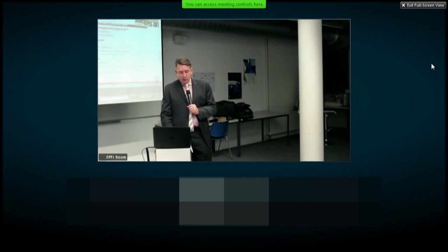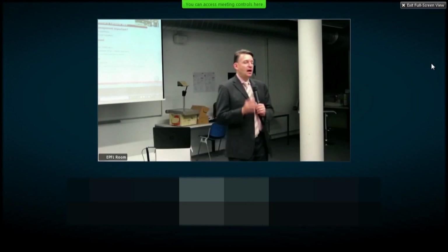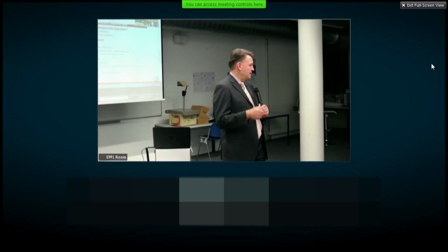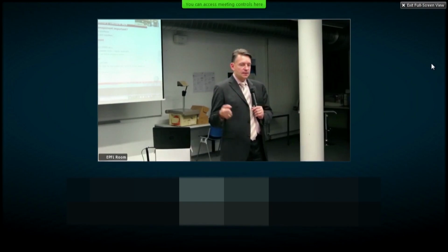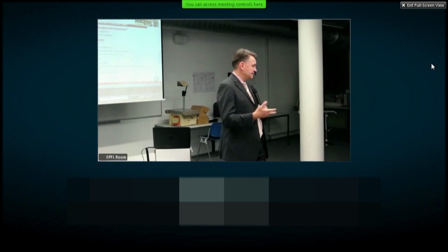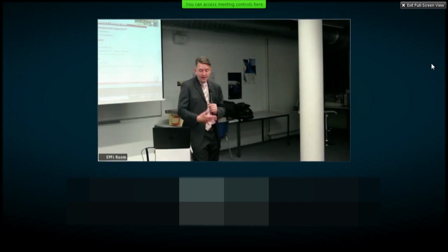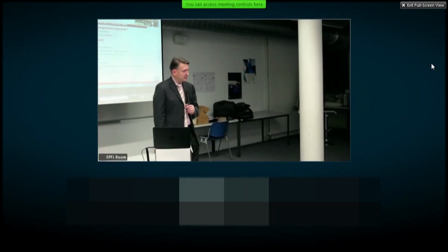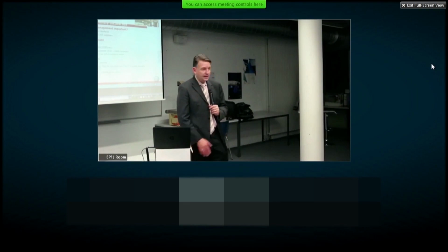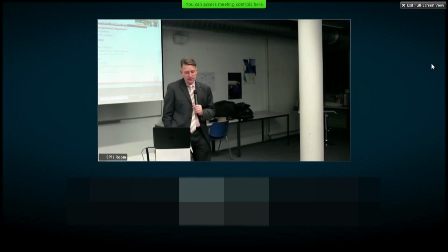Okay, and then finally, the point about system integration. Do not just do it randomly. Think about how you will assemble the system physically. How are you going to connect all your electronics, the consumables? How will you load your software? How will you test it? We'll talk about testing, verification, and validation next week. But the way in which you integrate, the sequence of integration, could be very important. And it's a pretty active area of research. So in system engineering, research is really understanding and modeling system integration as something you can optimize.